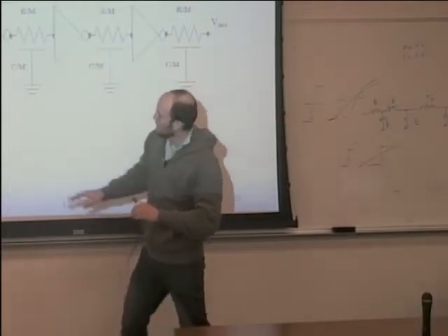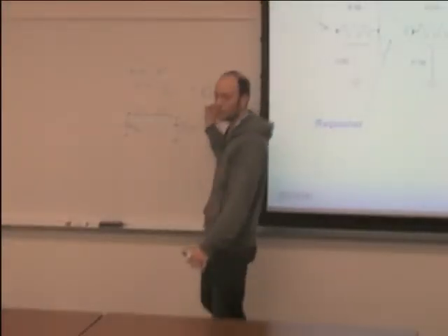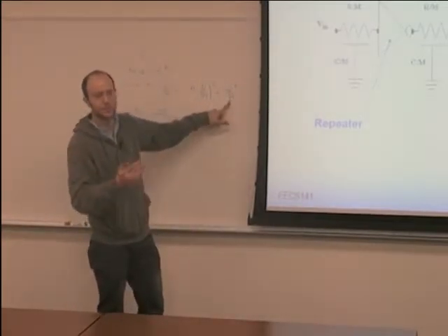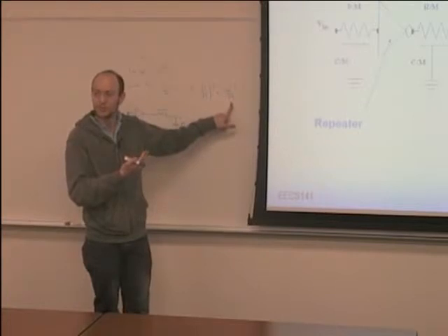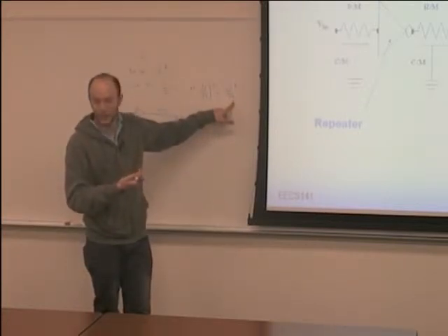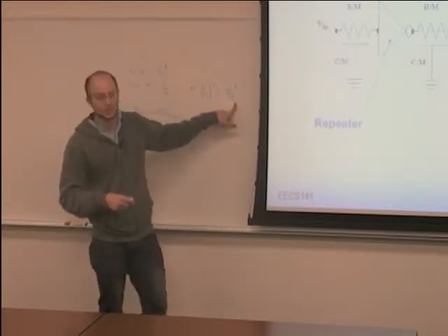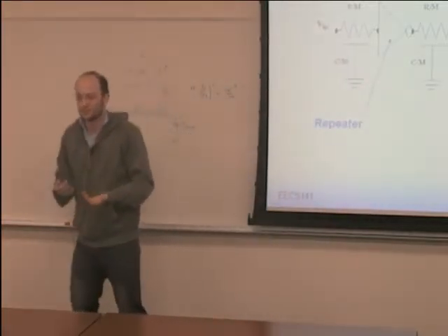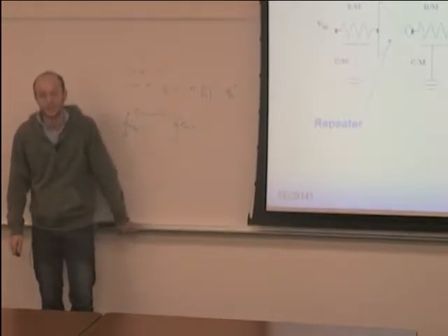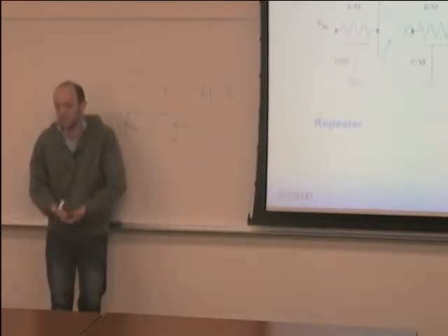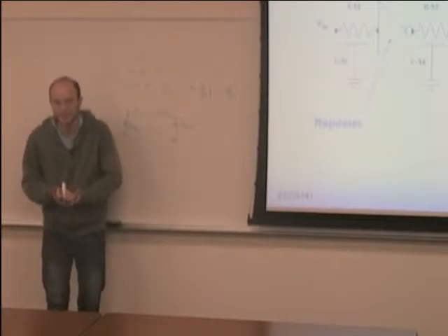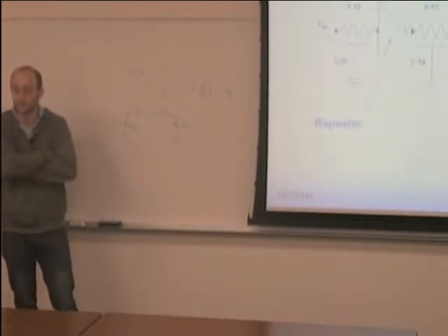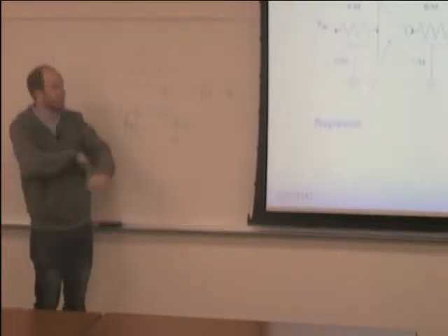But then this will tell you that to make the delay as small as possible, you just choose m equal to infinity, right? So you put an infinite number of buffers. So this doesn't work because the buffer doesn't have 0 delay. It has a finite delay. Correct?